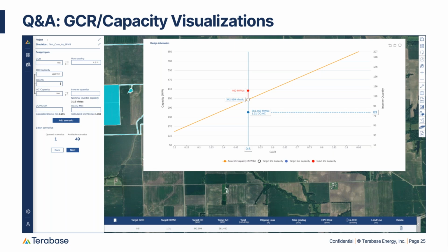You can then take that a step further, and if you say you have 20 different scenarios and you want to compare maybe the top couple or the lowest LCOEs, you can actually click the compare button, which is also on that scenario tray, and you can choose the scenarios you want to compare. That'll pop up an additional screen where it will show more detail of those different layouts side by side. It'll show details about the BOQ, about the costs, about different quantities of equipment, etc. And you can either view that in the UI, or you can create a downloadable Excel deliverable based off that.